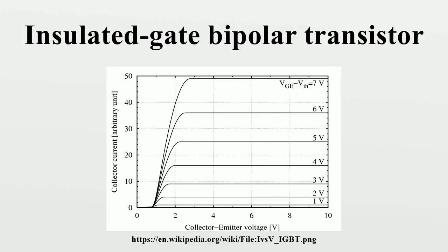However, this resultant reduction in on-state forward voltage comes with several penalties. The additional PN junction blocks reverse current flow. This means that unlike a MOSFET, IGBTs cannot conduct in the reverse direction. In bridge circuits, where reverse current flow is needed, an additional diode is placed in parallel with the IGBT to conduct current in the opposite direction. The penalty isn't overly severe because at higher voltages, where IGBT usage dominates, discrete diodes have a significantly higher performance than the body diode of a MOSFET.